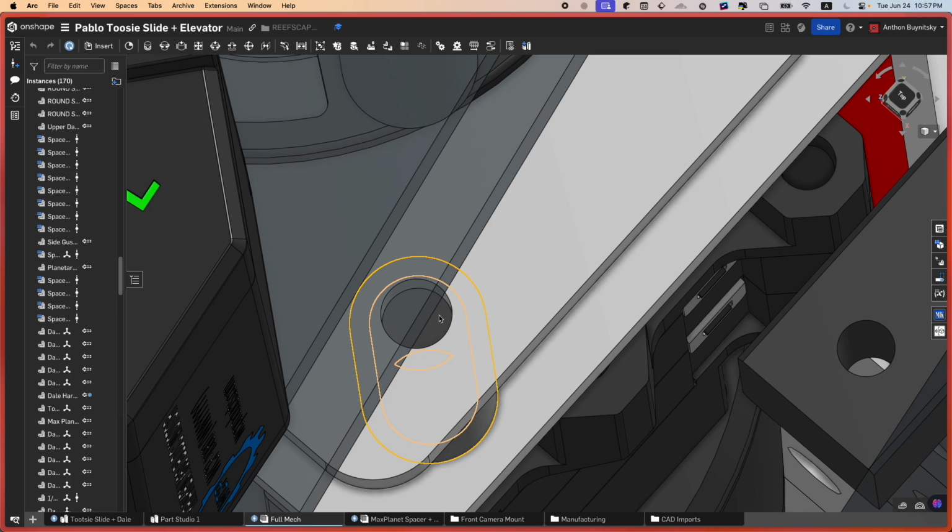So the tolerances for each material largely depend on how it's being manufactured. Like what Anton was saying with 3D printing, we use fused deposition modeling, where it sets down a melted layer of plastic and waits for that to essentially harden before it puts another layer on. Due to thermal expansion, plastics will expand and contract due to temperature changes.